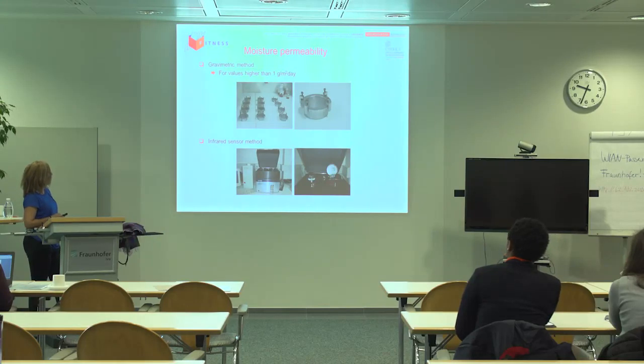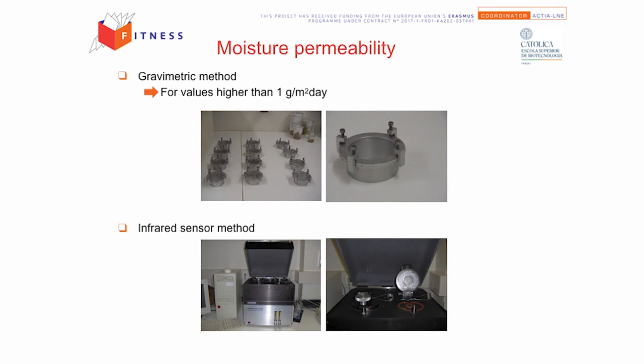To moisture, how can we measure the permeability? In this case, to moisture, we have some simple tests like these cups where we put the material in here. We put inside some material that is hygroscopic, or we can also put water, and we follow the weight gain or the weight loss with time, and with the slope then we can calculate the permeability.